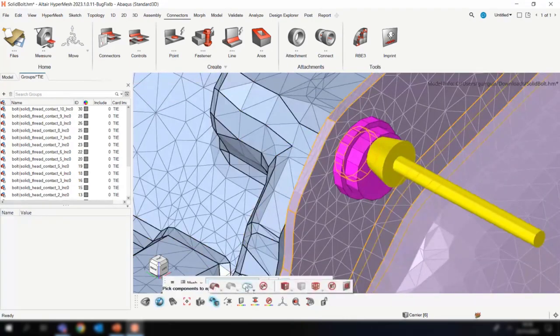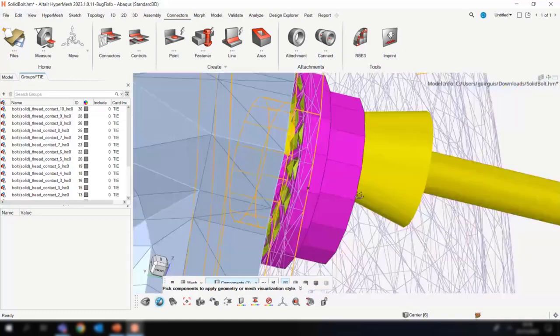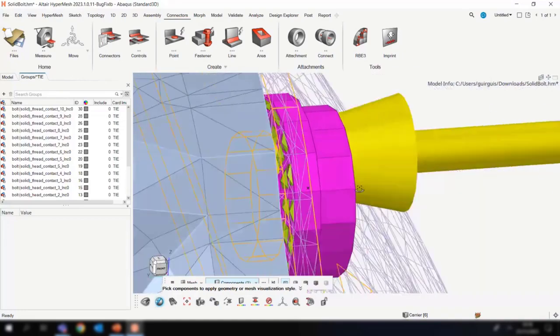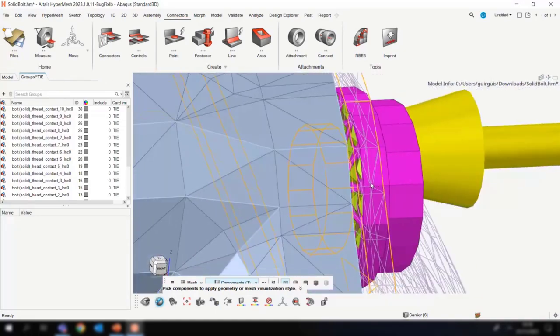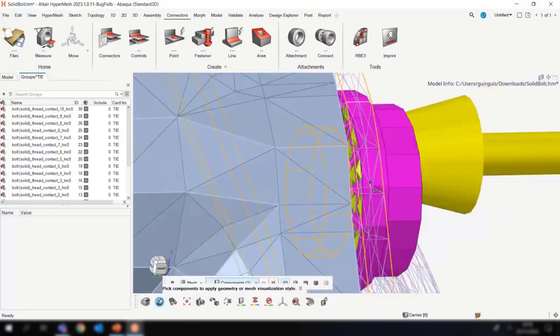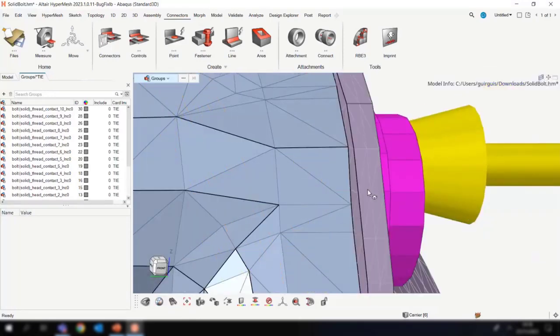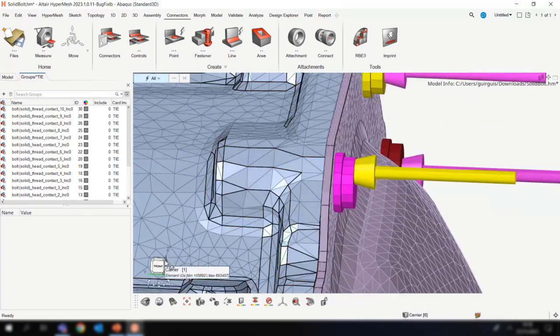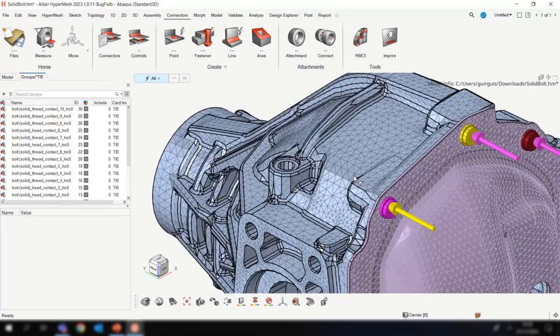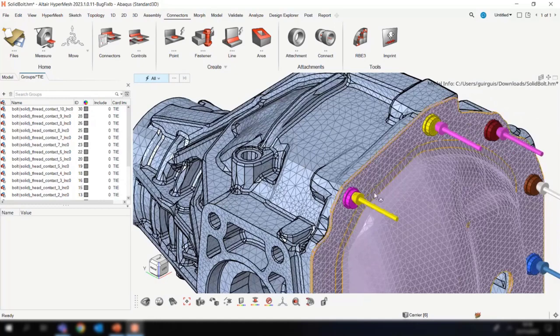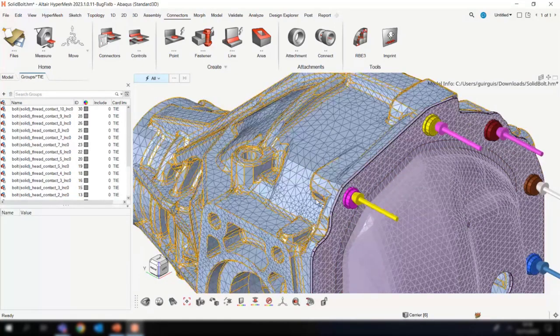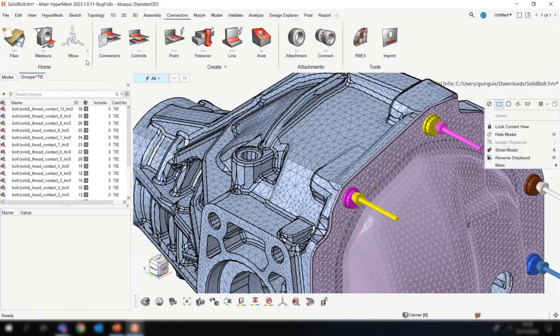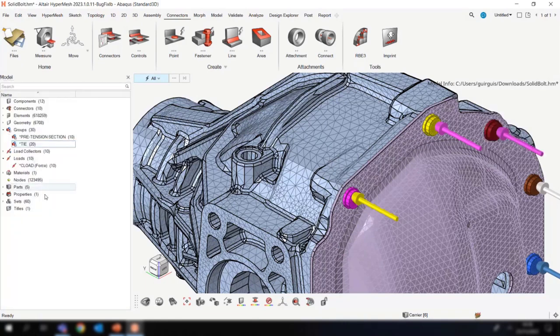If we look at the contacts, and turn the geometry off, we can see that the contact is generated under the bolt head as well, to ensure that your bolt head is tightened. For anything more than a 2T stack up, we will manage the contact at the bolt head and the contact at the thread. The contact in between the layers, the user will need to specify themselves, because that might be something specific to your setup.